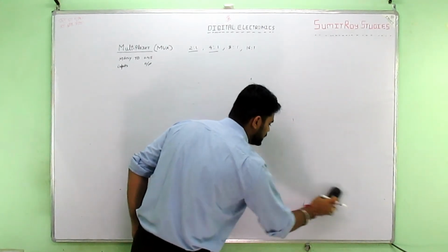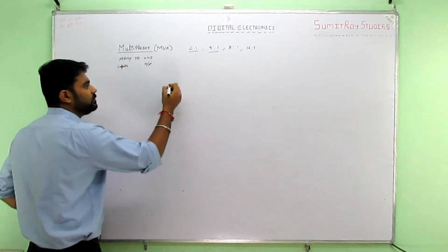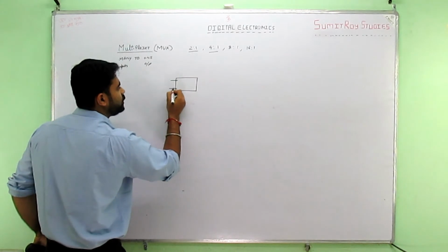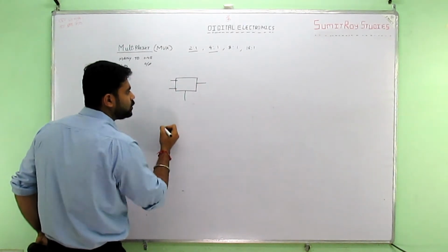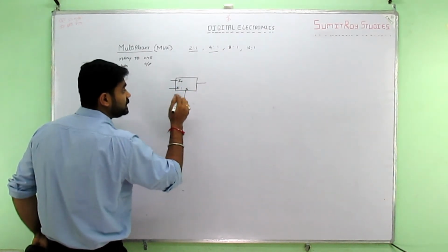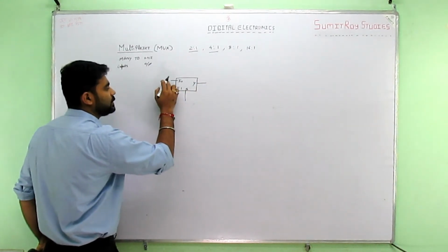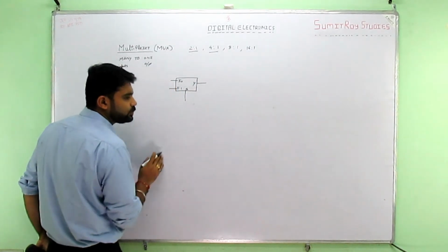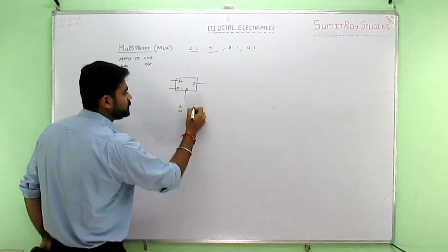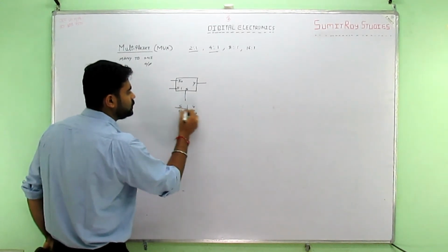So, 2:1 multiplexer. Now what is a 2:1 multiplexer, as I have given you just an overview. There are two possible inputs, one selection and one output. Let us name them I0, I1, let the selection be S, and let Y be the output. So based on this, if S is 0, then output will be I0, if S is 1, output will be I1.